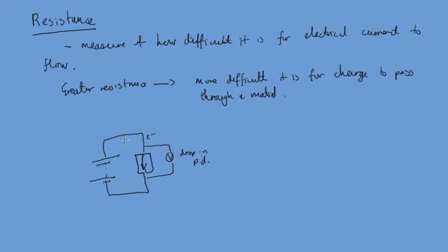Copper's got a low resistance, so that's why we use it, because we can't afford to have gold cables. If you've got a very, very sensitive circuit, you would need to pay attention and factor in the resistance of the cables. But for most of the circuits that we will encounter, that's not a problem.